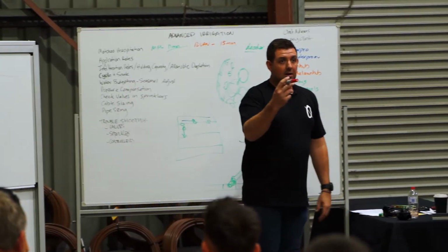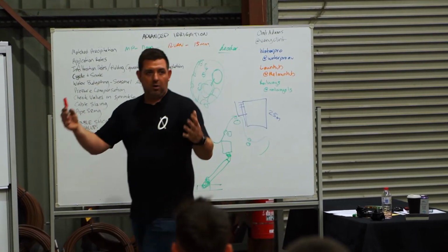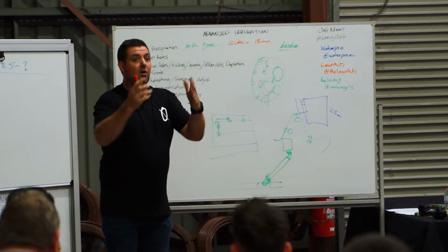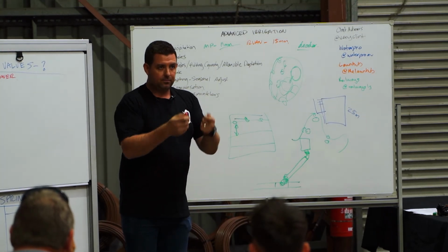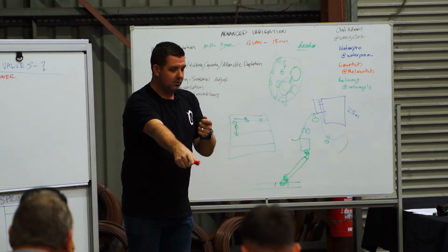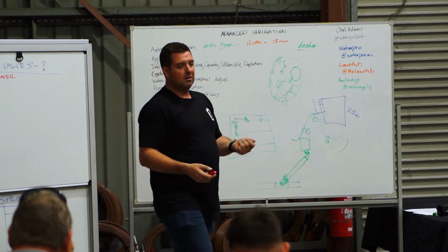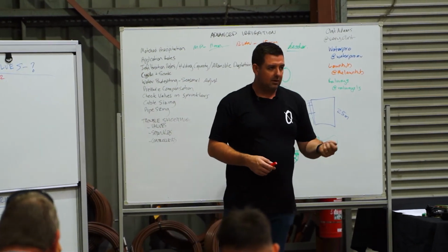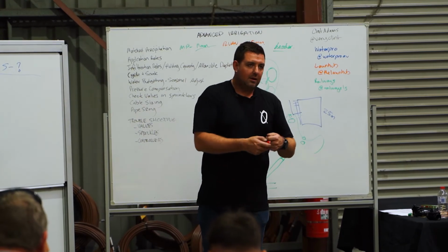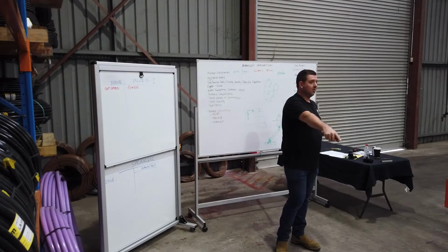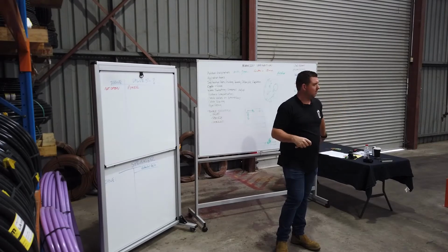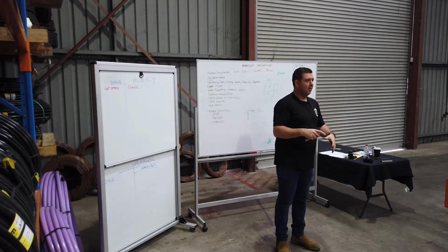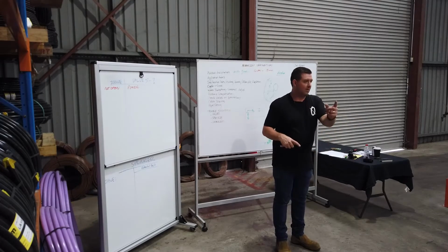So obviously, if it's an electricity issue, we're going to go to the controller and have a look and say, it's on, cool? Is there power coming out of the ports that the valve's meant to be running to? Now, if you don't have a multimeter, and I'd say it's probably a good idea to have one if you're going to be doing regular irrigation, you can do an ohms resistance test on the coil, as in with no power running through it, you put your probes there and test the resistance. And if you get, I think Matt was saying yesterday, like a 20 or a 25, electricity is getting to the coil and back, so that's fine.